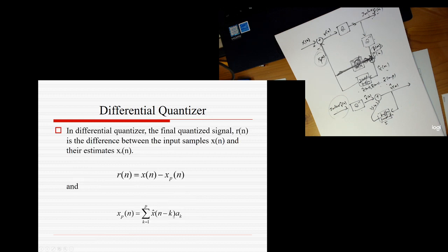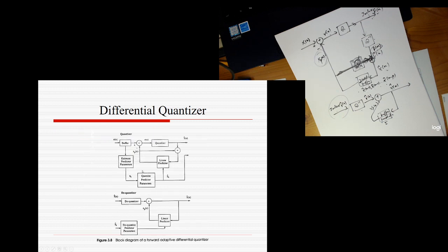Sometimes the decoder wants to know the coefficient, because the encoder and decoder coefficients should be known in advance. So here we have a buffer according to the input data, maybe one speech frame, which could be 20 milliseconds, that would be 160 samples, or 30 milliseconds for one buffer, which would be 240 samples.